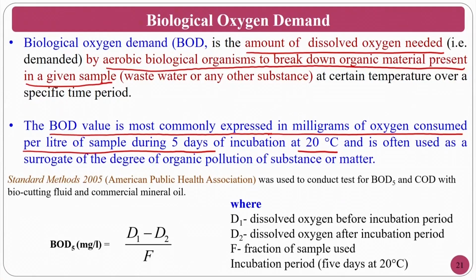Like the IAS examination and other examinations, there is a preliminary test as well as a main test. So, you can consider this as a preliminary examination, and ultimate biodegradability is nothing but our mains. The standard method of the American Public Health Association was used here. Normally BOD5 stands for the biological oxygen demand test that you are doing for 5 days, and COD is nothing but chemical oxygen demand, that is the ultimate one.